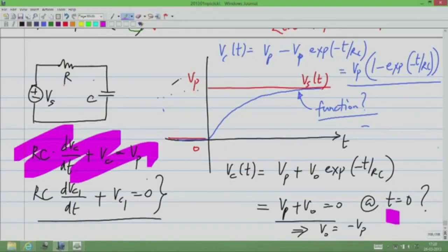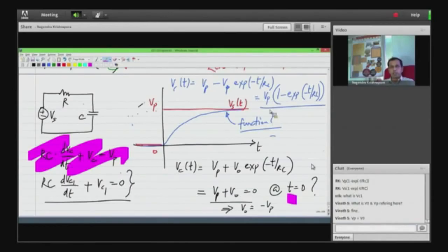So okay then, we have looked at the RC circuit. It is governed by a differential equation. We have solved for it intuitively. We know what it means. Okay, that is very important actually. We have of course taken a special case of only constant inputs. When I say constant, it jumps from one constant value to another constant value. Now if it does that, what happens to the capacitor voltage, and we will see later that this happens to every variable in the circuit, is it undergoes some change with some exponential argument, and the argument inside will be minus t by RC or minus t by some time constant.